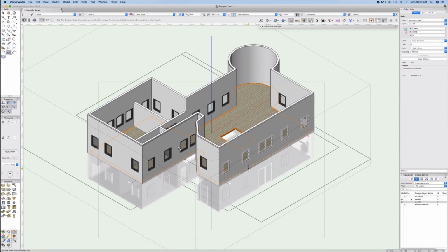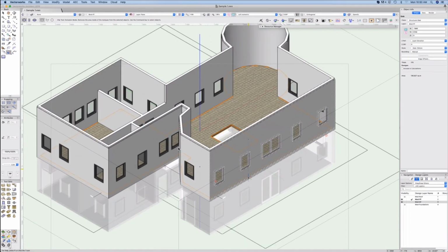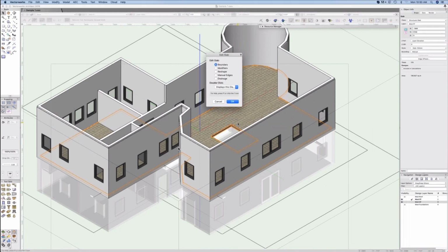Awesome. How about if you got that hole in the wrong place? Yes, and you want to edit it now. What do you think you do if you double click? Well, I just told you now. What do you think you do? You have to double click basically. So X, double click, edit the modifiers. These are called modifiers, these things. Click OK. Yeah. What's displayed? Don't worry about that. You just leave that. Yep. Click OK. There we go.